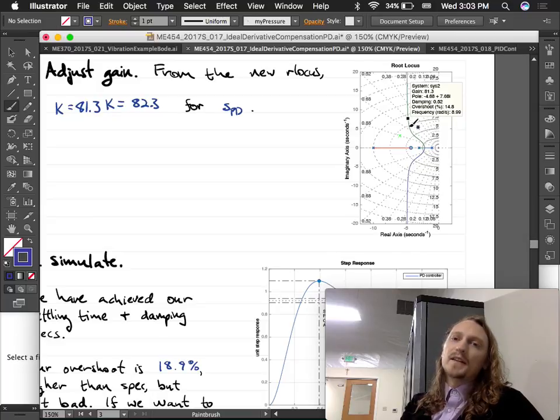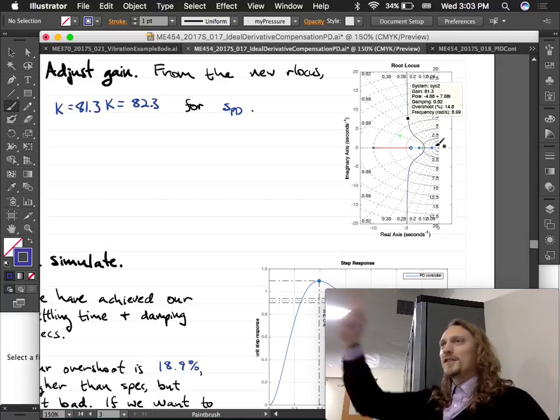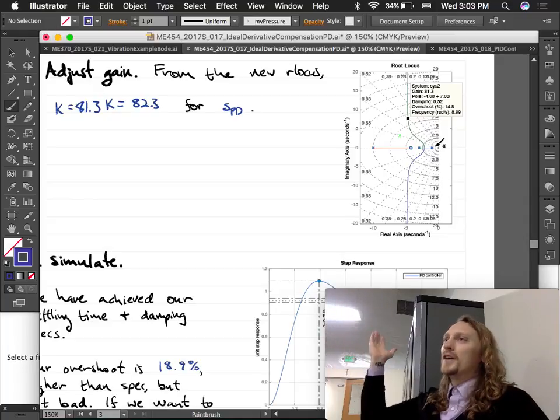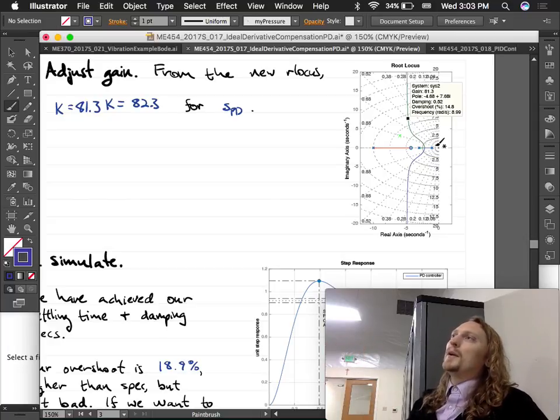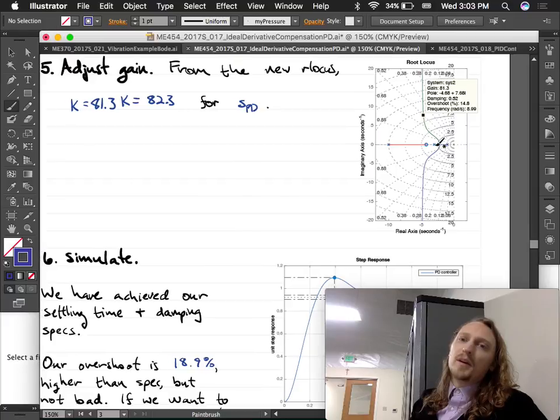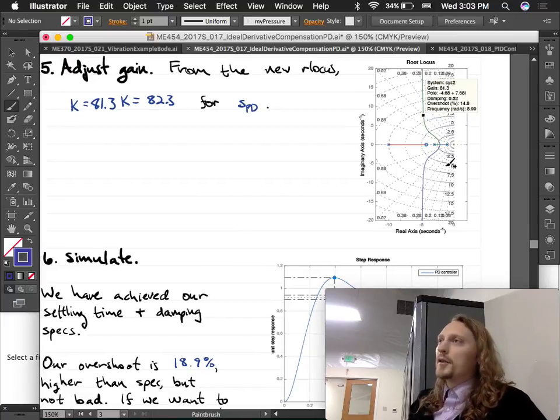We would sacrifice a little bit of settling time because it's going to move a little bit to the right. See how this is sort of sloping that way? So we could go back though and start with the previous step, know where it's going now, and be a little bit more conservative with our estimate. And then maybe we should try our test point. We could maybe multiply it by 3.5 or something like that. And then even if we have to give up a little bit, we can give up a little bit. It's not a big deal.